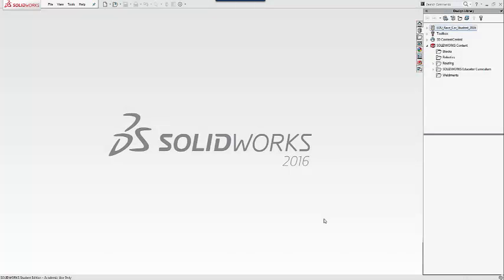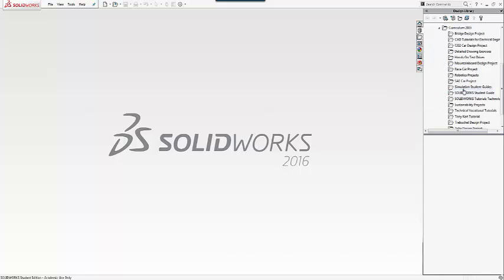This video will give an introduction to 3D printing a SOLIDWORKS model of a Racecar using a Makerbot. This model can be found by first running SOLIDWORKS software, going into the design library, then clicking SOLIDWORKS Educator Curriculum, specifically 2015, and then select the folder labeled Racecar Project and extract the appropriate files.